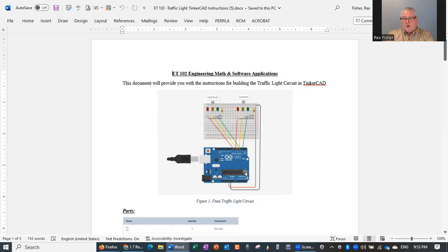Now, the way the wiring works, this red wire is a 5-volt wire. There's a 5-volt output right here on the Arduino board. That's a 5-volt output. And it comes up here, and I'll show you in a little better picture how that's connected. It connects to a resistor, and the resistor connects to these 3 lights. So when you want to turn, let's say, the red light on, this red wire here comes to an Arduino control pin, that Arduino control pin will be grounded.